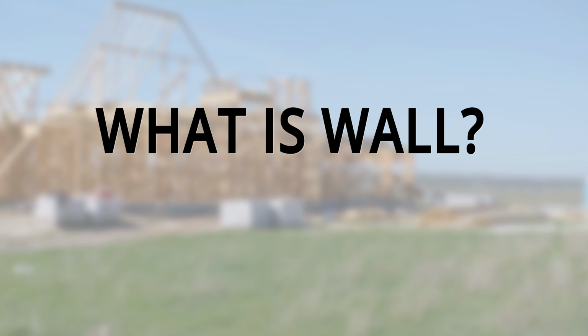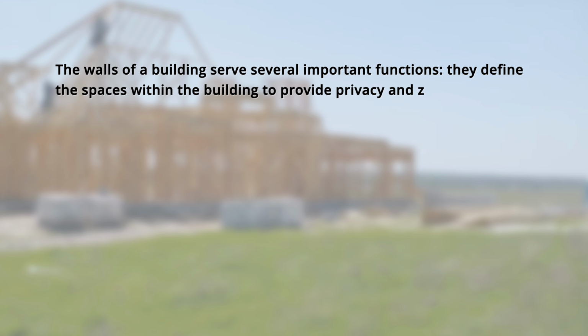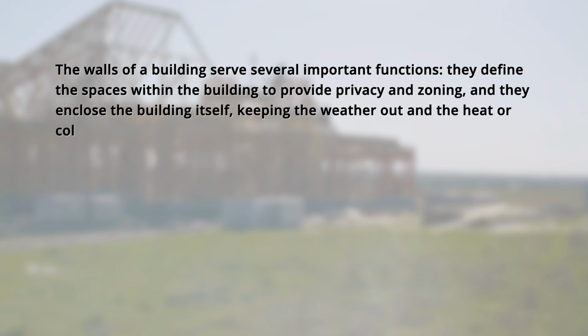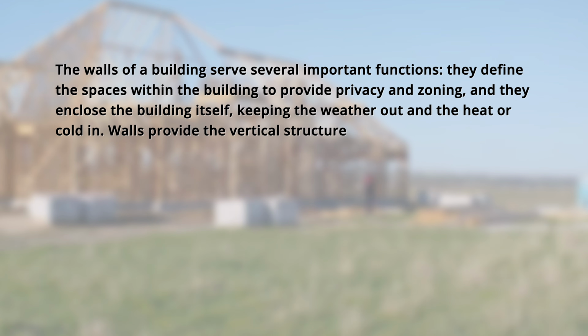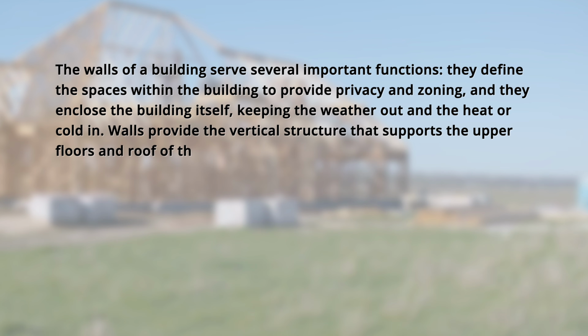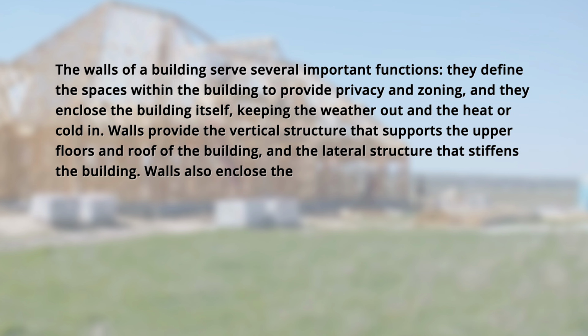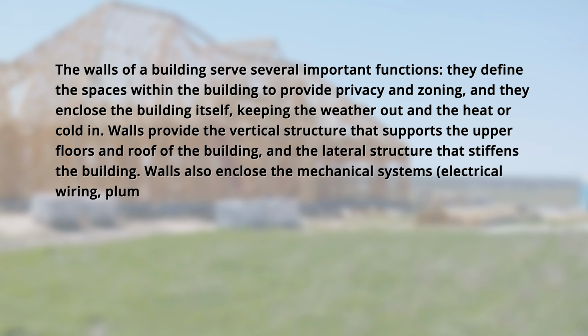What is a wall? The walls of a building serve several important functions. They define the spaces within the building to provide privacy and zoning, and they enclose the building itself, keeping the weather out and the heat or cold in. Walls provide the vertical structure that supports the upper floors and roof of the building, and the lateral bracing. They also enclose the mechanical systems, electrical wiring, plumbing, and heating.